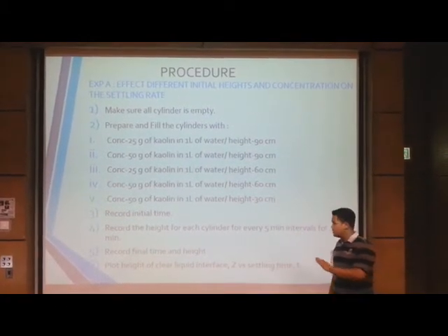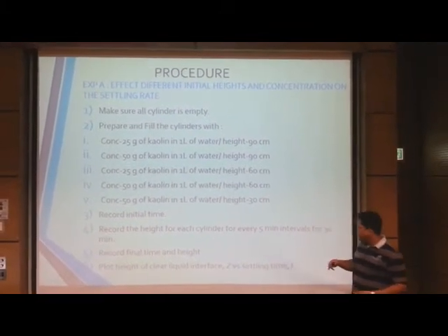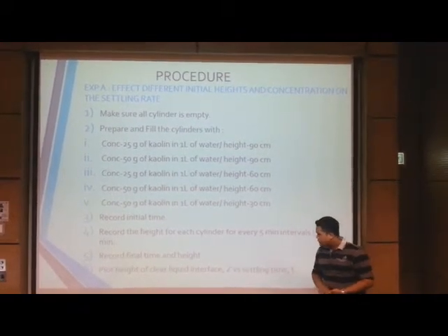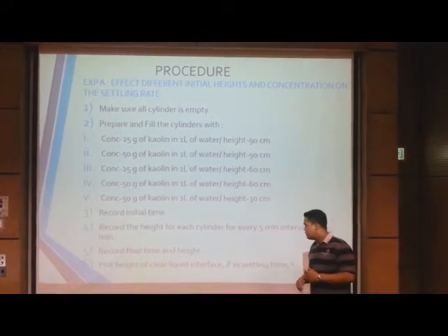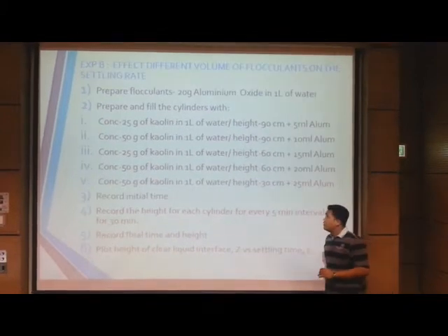Then we record the initial time, and for each 5 minutes, for 30 minutes, we record the height for each cylinder, and then the final time and height are recorded. And for the graphing, we plot the height of the clear liquid interface Z against the time. For the second part,